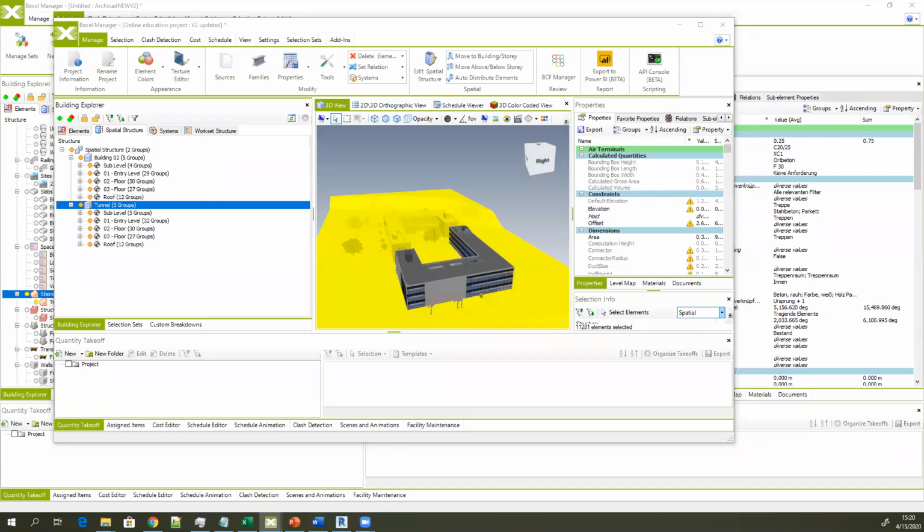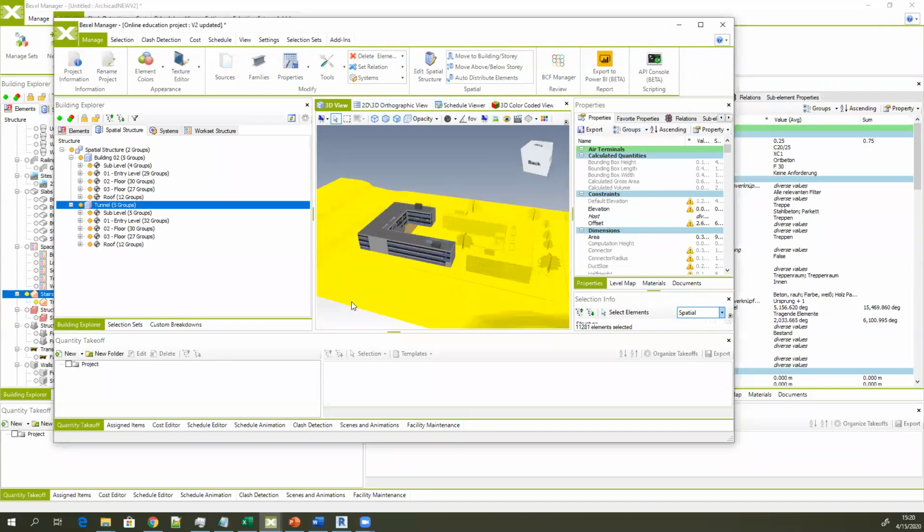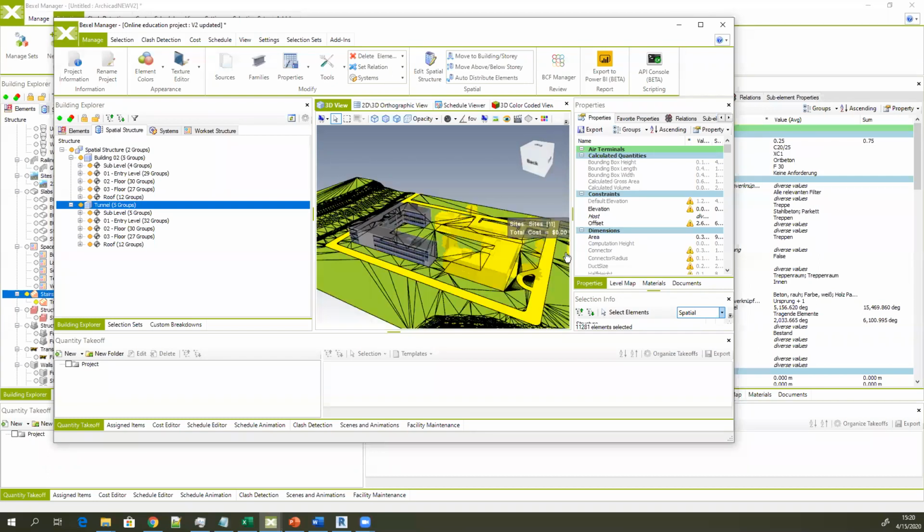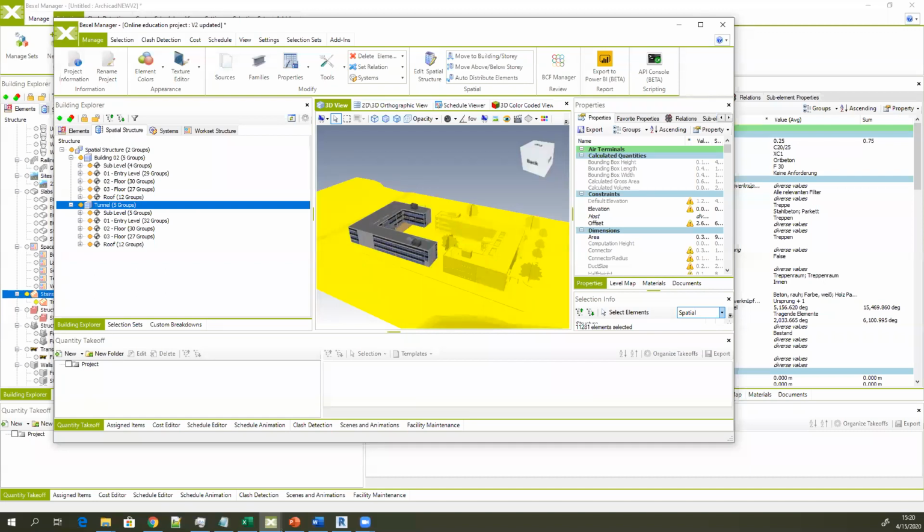The next question: why, when I publish a Revit model to BX3 and open it in Bexel Manager, does it not show Uniformat, MasterFormat, and custom sequence? Because you did not enter these properties within your Revit model. This sample model is created in Revit, and in Revit we added some additional properties or attributes, and then these properties are exported. So if you want to get Uniformat or MasterFormat or any other additional property, you have to specify that in your authoring tool.